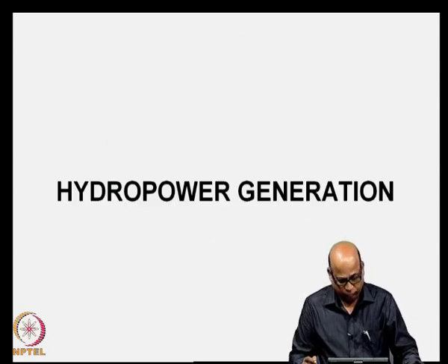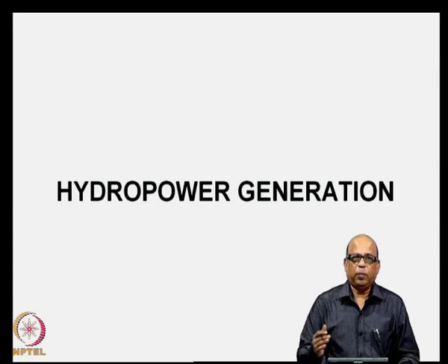All right. Now, we will move to a different topic, but just let me summarize what we did in the optimal reservoir operation. Initially, we considered a single reservoir and then looked at the standard operating policy and then formulated a linear programming problem after going through the sequent peak algorithm, etc. So, the linear programming problem specified an optimal operating policy for a given objective function. That means, you specified the objective of operation and then for that particular objective you achieved an optimal operating policy in terms of the end of the period storage that needs to be maintained.